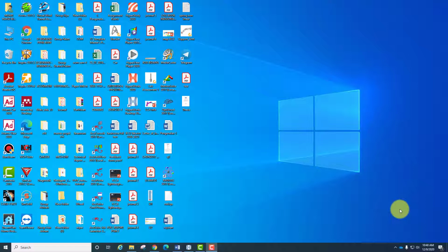Okay, this video session is about how to perform the full vehicle analysis using MotionView. Before this, in the previous videos, you already learned how to run the suspension analysis for static ride, and also kinematic and compliance. So this video is purposely on how to run full vehicle analysis using MotionView.